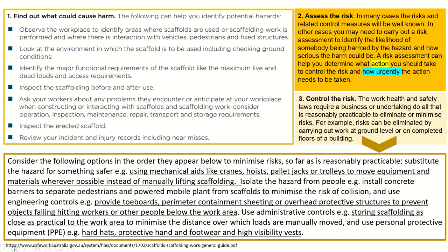So you need to go and observe the construction site where you are going to do the scaffolding and where that temporary structure should be erected. You need to evaluate the construction site, the ground conditions and weather condition for that specific day you are going, or day, months, weeks that you are going to do this scaffolding, and use it.